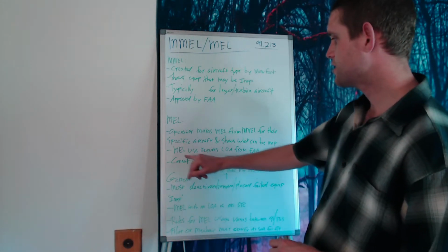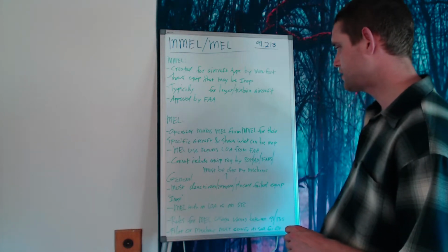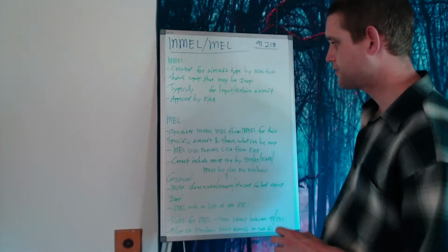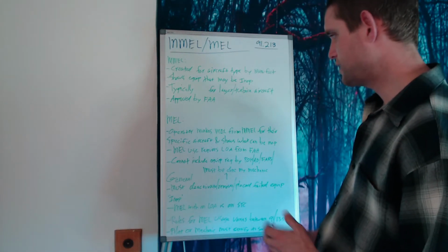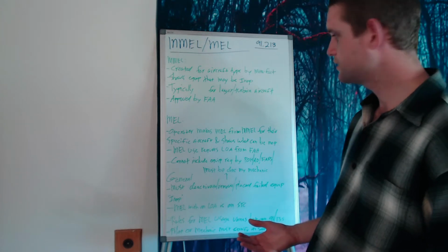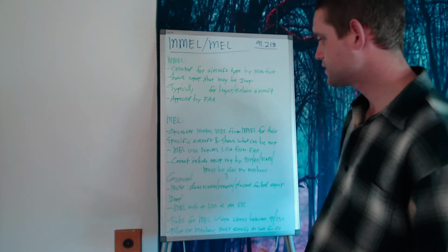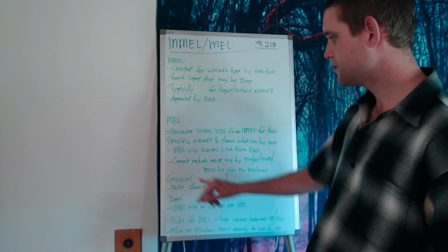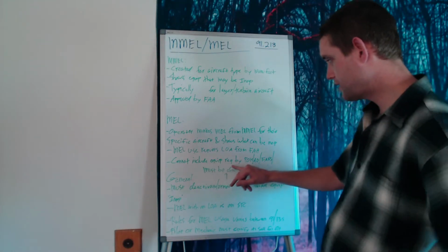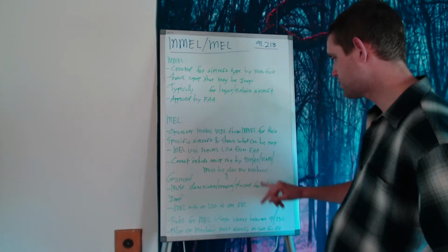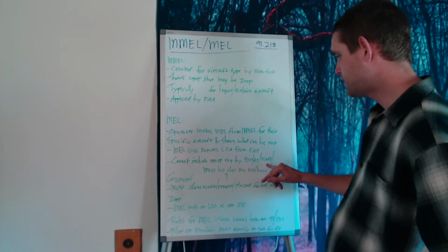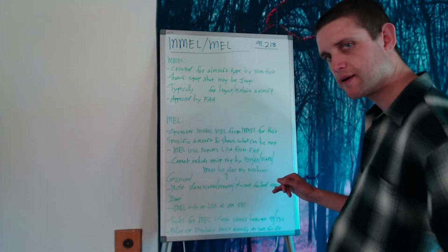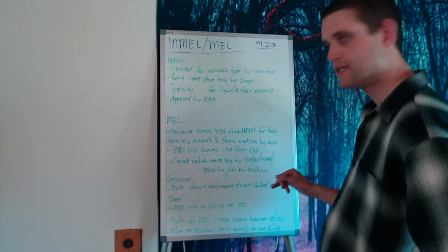If you do have an MEL, it requires that you also obtain an LOA, or letter of authorization, from the FAA. It's basically saying that the FAA has inspected your minimum equipment list and approves it for use. The MEL cannot contain any equipment that is otherwise required by the Pilot's Operating Handbook, Airworthiness Directives, FARs, or any other equipment that the pilot in command considers necessary for safe flight.